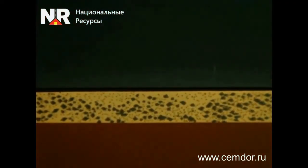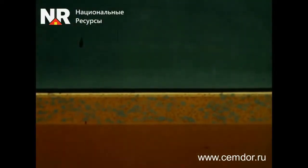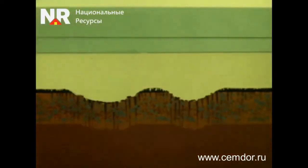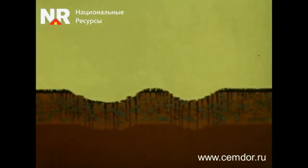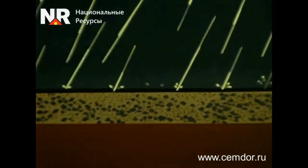In dry conditions, well-compacted soil can already be used as a road structure. However, moisture penetrates most soils, causing a loss of stability. Under the influence of loads, the road surface deforms and tends to break down. In other words, the soil becomes plastic and loses its strength. This problem can be solved by adding cement to the soil composition. It binds all the soil particles into a monolith, giving the material structural strength. Moisture penetration into the soil cement structural layer is minimal, and it retains its strength and stability under any conditions.